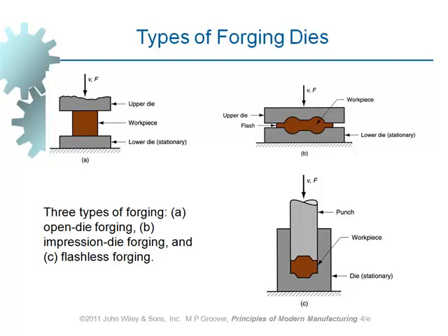That one is also a very common method. In this one, indeed, the material is not taking the final shape. What is happening is that we are just improving the properties of the material, by subjecting it to pressure and deformation. We are reorienting the grains, the crystalline structure of the grains. By doing this, we improve the properties of the material.